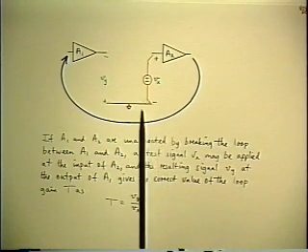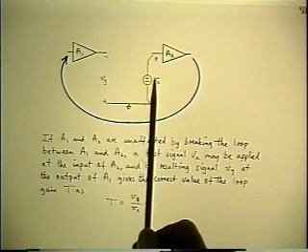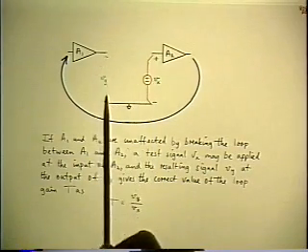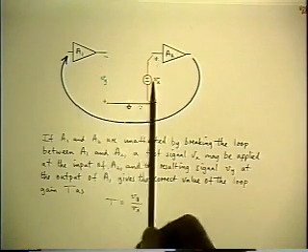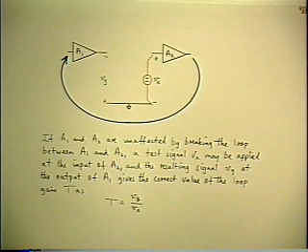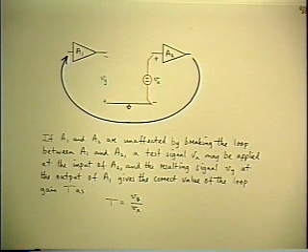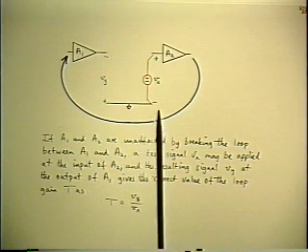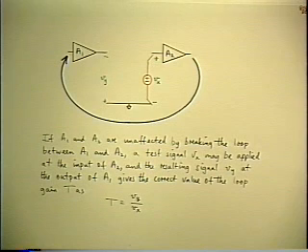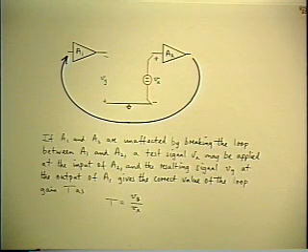If you do it this way, you usually end up spending 90% of the measurement time reestablishing the operating point and only 10% making the AC measurements. And you don't get very good answers anyway because of the drift in between. So even though in principle on paper this is very simple, in practice it's quite difficult to implement. So what I want to show you now is a very simple modification that totally bypasses that problem. You can set it up in the following way.